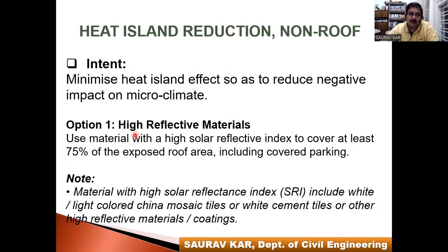So option one. What are the options the IGBC has given? High reflective materials. You have seen in the video which I showed you previously, they are using glass claddings and white tiles because maximum heat and sunlight rays will be reflected. So high reflective material is very important. You should not use any paint or color or material which absorbs huge heat.